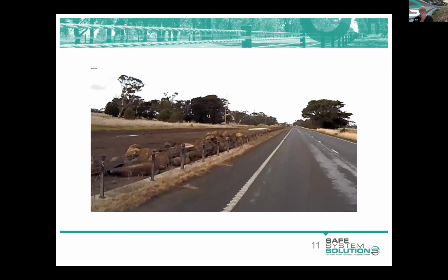And look, I hope this comes up okay on people's screens. This was a construction of an overtaking lane on the Princess Highway between Warrnambool and Geelong. What the works were doing was preliminary earthworks, and so there was really no effect on the through traffic. But as you can see, there's wire rope there, but they've come across rock and they've actually stacked it close to the wire rope. And the outcome of that is you're actually taking away what the wire rope is put there for. You've actually created a hazard.